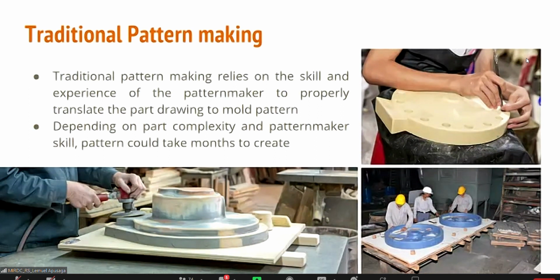But along that process, once he assembles all those shapes to make that full part, it might be dimensionally accurate for each shape that he drew. But when he puts it together, he might not have been able to consider the concentricity of the flanges or the wall thicknesses of the parts. That may lead to problems in subsequent processes like machining.